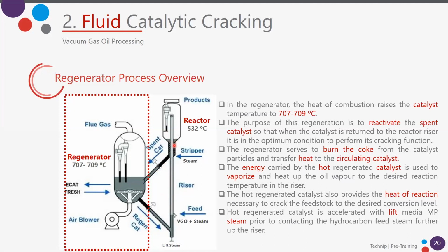Remember that this is like a fluid. It is in a fluidized state. So you will control the level here with this valve, and this other valve will be controlled with the temperature in the reactor, okay? Why with the temperature? Who gives the temperature to the reactor? The catalyst. So if you want more temperature in the reactor, you will have to have more catalyst here to heat your reactor. So these are very important valves in the system.